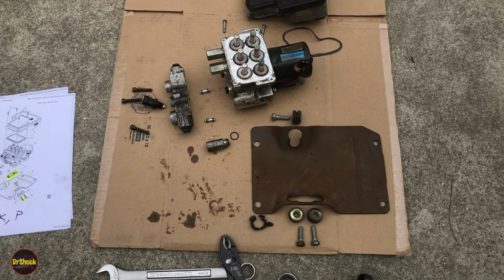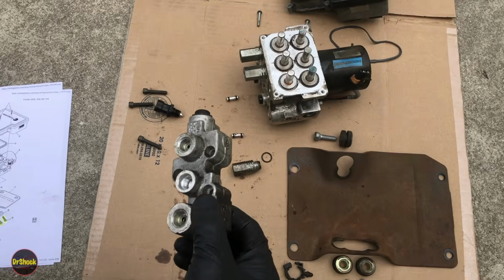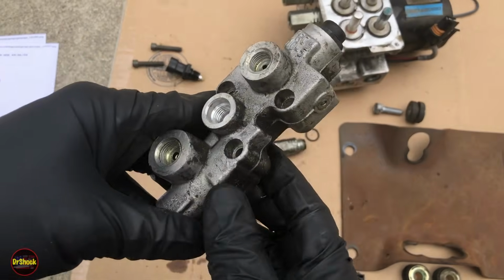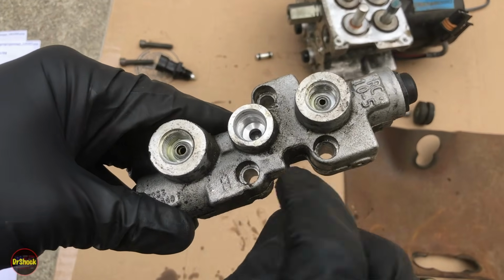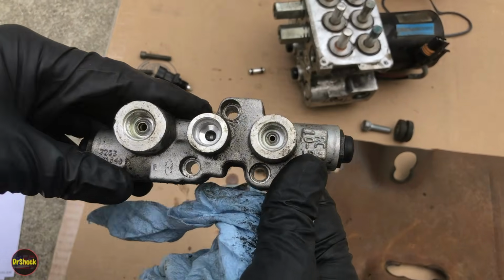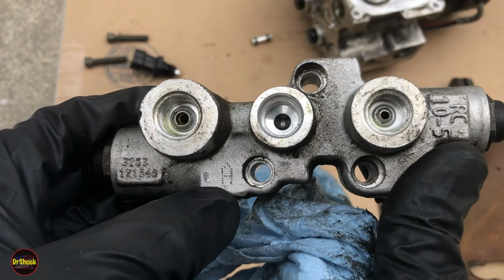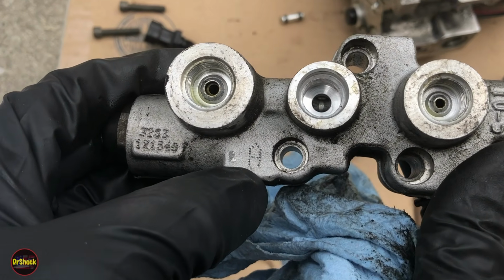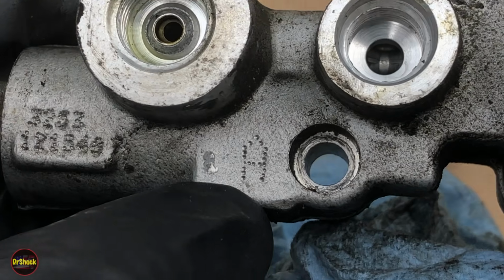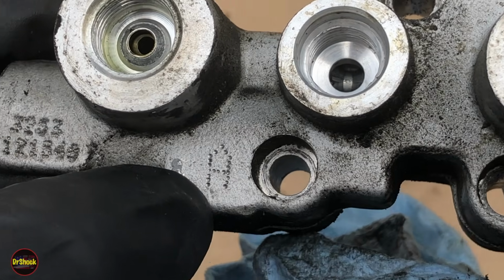And what I'm going to do is I'm going to show you how they differ. So start with the combination valve. In the combination valve, you can identify this part because it'll have a letter code on it. You can see this one's an A if we zoom in here. And a CK truck is going to have either an A, a D, an L, or an S, depending on the engine combination.